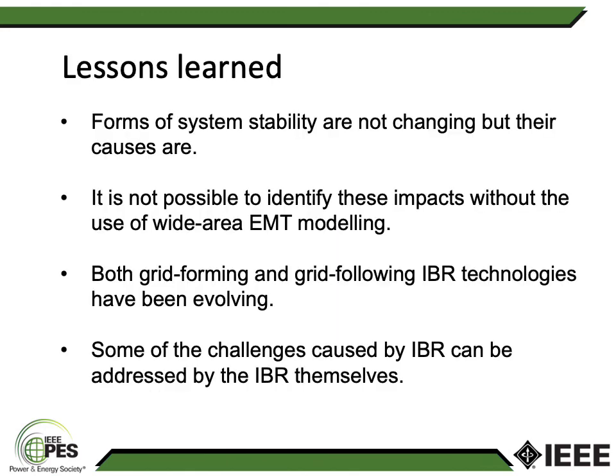To summarize some of the lessons learned, forms of system stability are not changing. We could classify these subsynchronous oscillations as converter-driven stability. The only difference is that as we are moving to a power system with much less synchronous generation and increased uptake of inverter-based resources, the causes of the same forms of system stability are changing. And without the use of wide area EMT modeling, the prediction of these forms of system stability, especially as it covers a wide part of the power system, would not be possible.